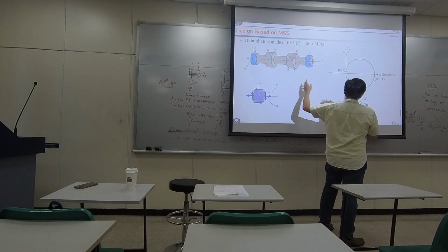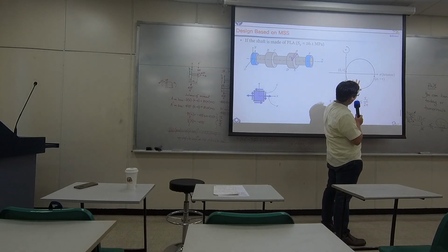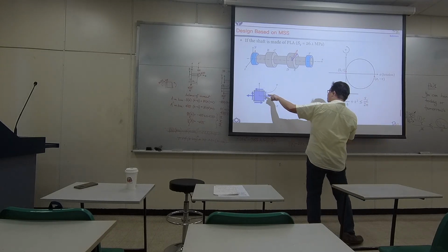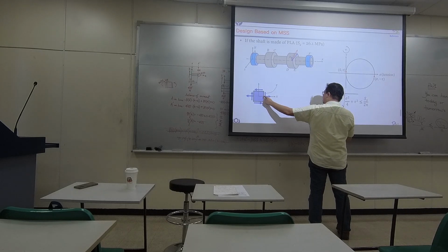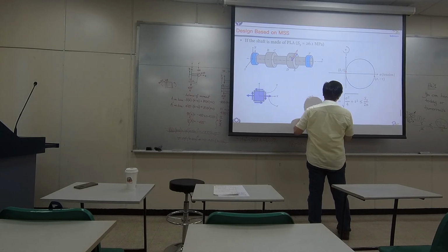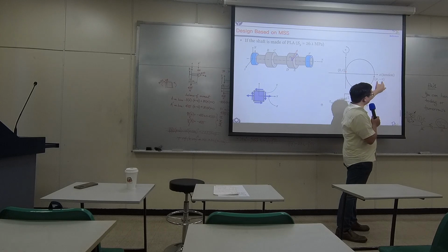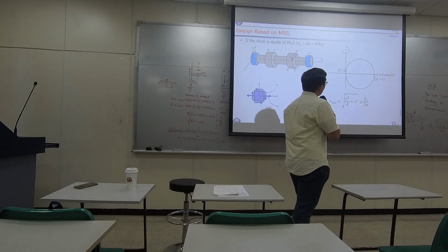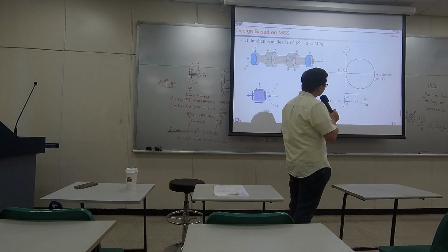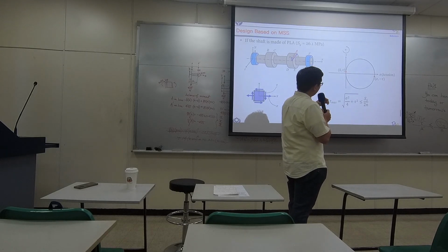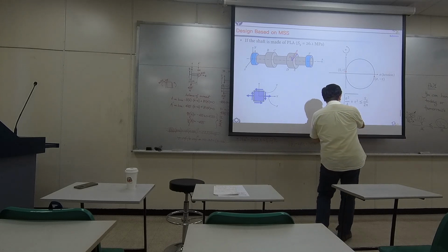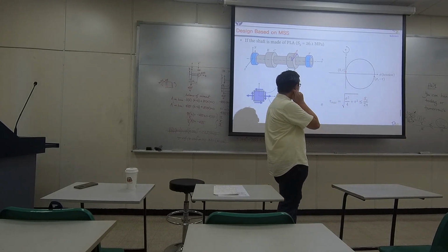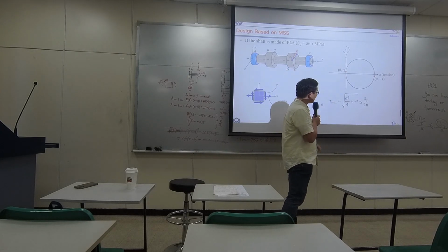diagram here. This is basically the Mohr circle, and this is representing the normal stress that you observe from the right, and the shear stress you observe on the right. Those values could be changed if you change something in your design. And what we would like to introduce right now in this particular diagram is that we want to study the equation over here of your maximum shear stress.